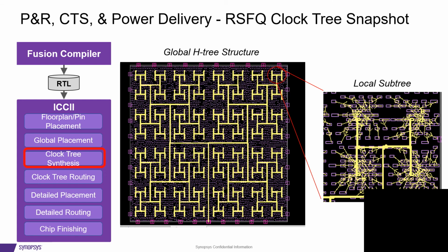What does that mean? It means that for all our standard cells, we've equipped each standard cell with a PTL transmitter and a PTL receiver. That isolates the timing of the cells from each other. That makes timing accountability extremely easy and makes automation much easier and possible.